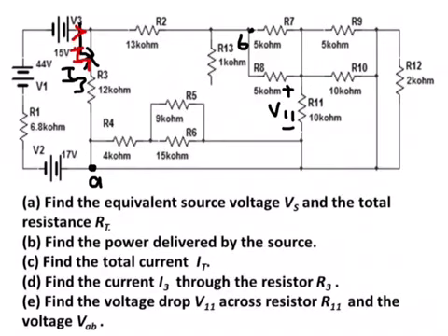So this means that R9, R10, and R11 share the start node and they share the end node. So R9, R10, and R11 are in parallel. What happens to R12? R12 is connected between this node and this node, but these two are shorted, as you can see. So R12 will disappear from my circuit. So we can immediately say that this branch is gone. I don't have this resistance anymore.